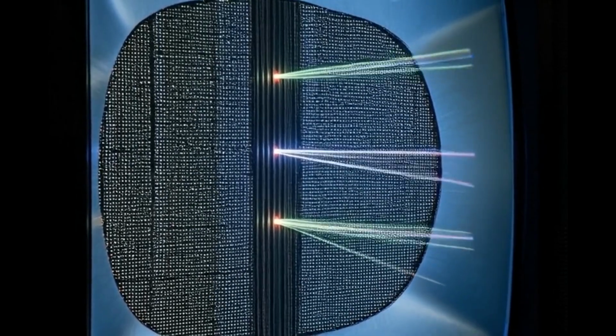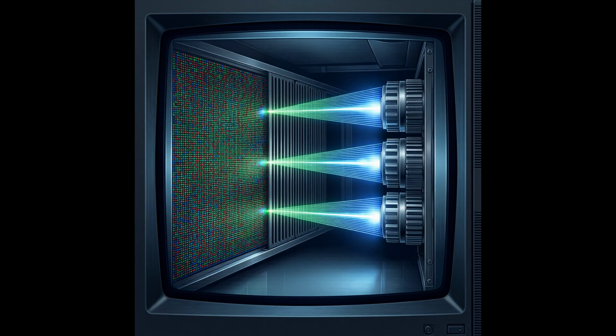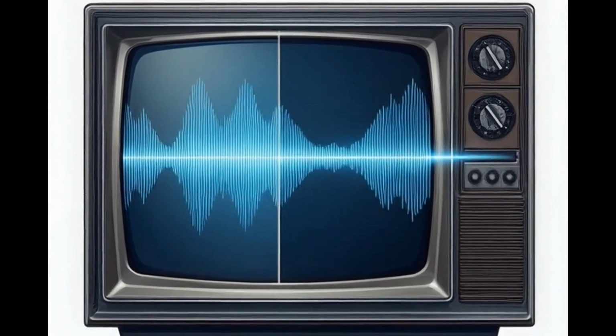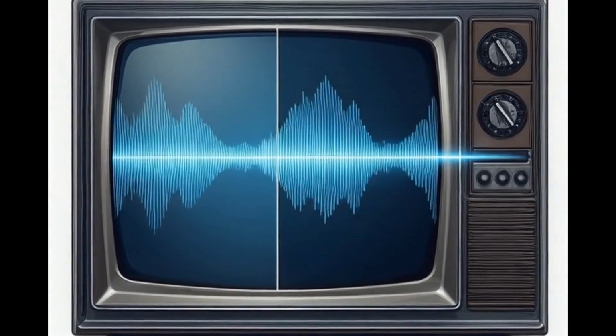This mechanical precision means even minor misalignment can cause color fringing or washed-out images, because the electron streams must maintain strict spatial correspondence with the underlying phosphor clusters. Understanding this physical separation mechanism sets the stage for examining how electronic signals synchronize these beams to paint coherent pictures across the screen to reconstruct a coherent image on an old television screen.